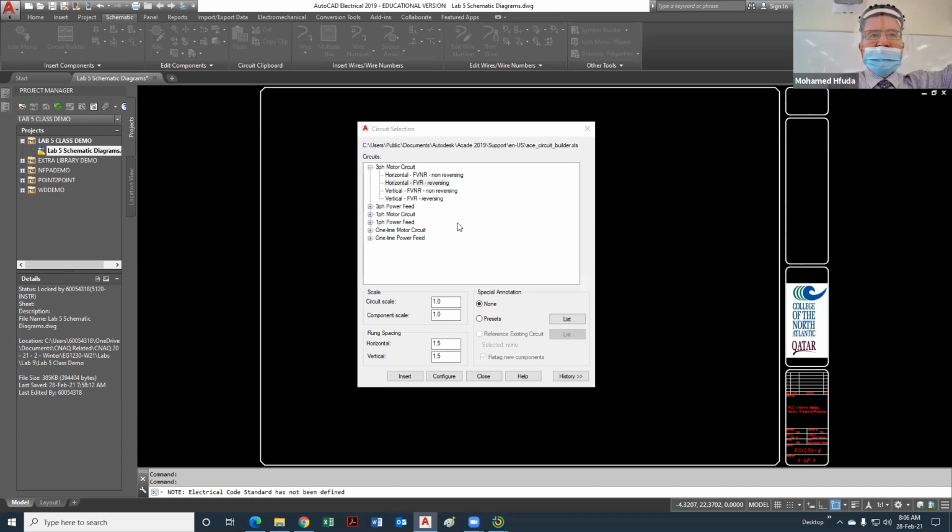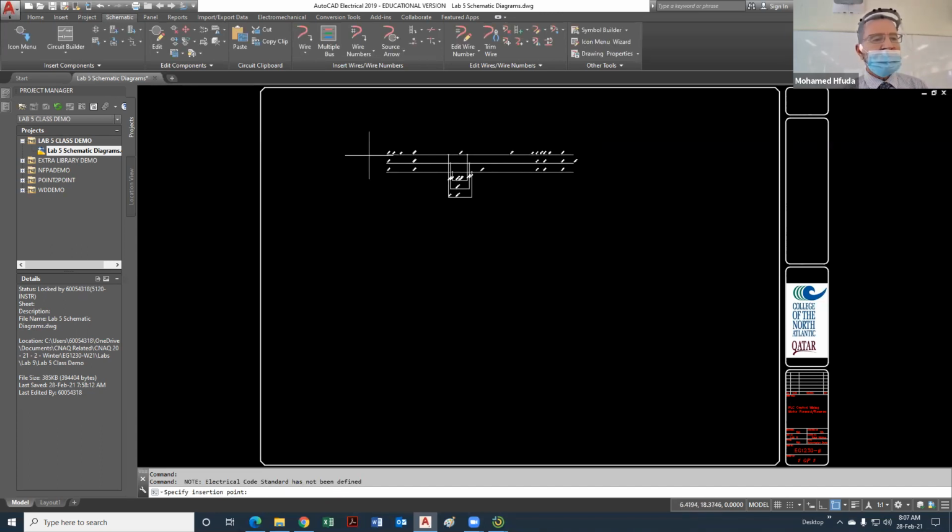Because when you look at oil fields, they have local stations. They're not connected to utility. Utility is sometimes called the infinite bus. You have huge capacity available. So it's like you have a big tank and you take a small load, it's not going to affect the level. But if you have a small tank and a big pipe and you open it very quickly, you're going to see the level drop. Same thing with generators.